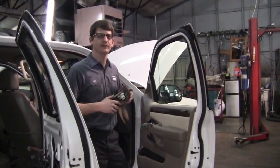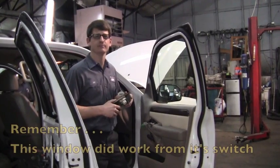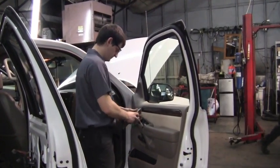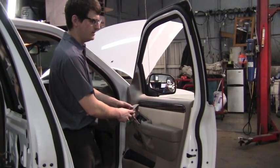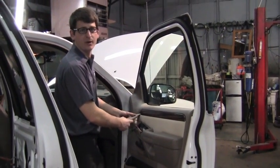We're going to take the right rear switch, which is in question, and plug it into a circuit that is known to be good and see what result we get. There we can see the right front window going down and the right front window going up. So we know that our switch is not the problem on the right rear.